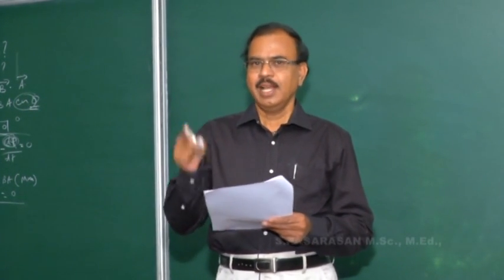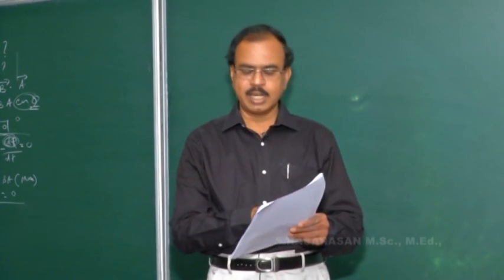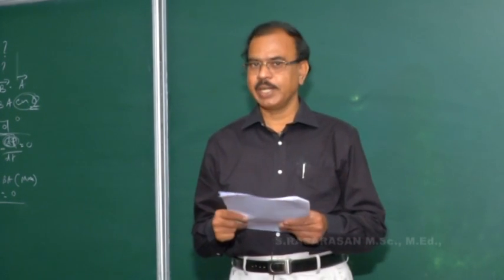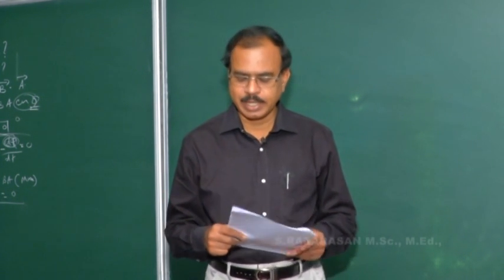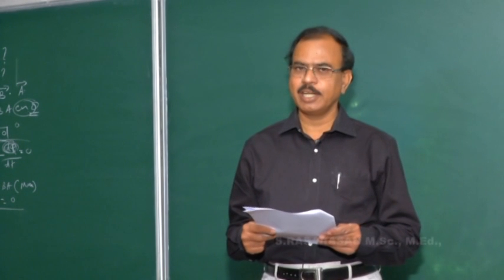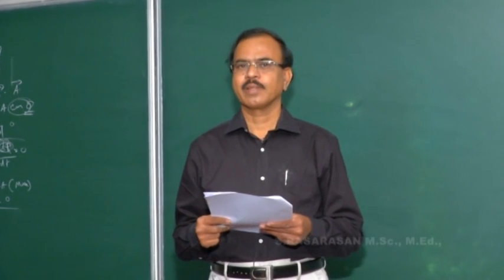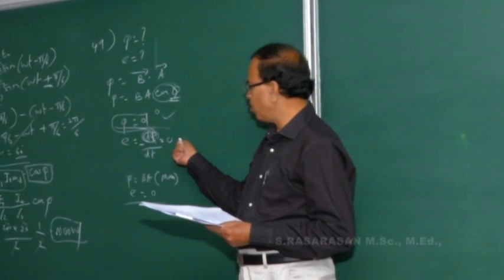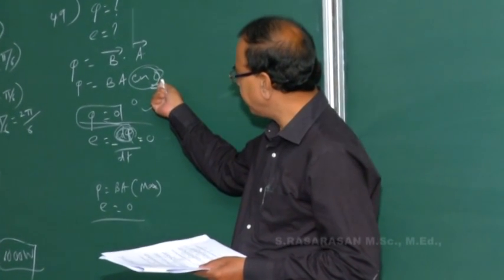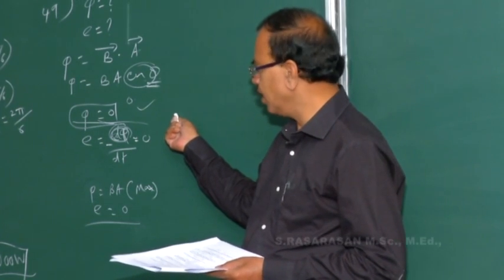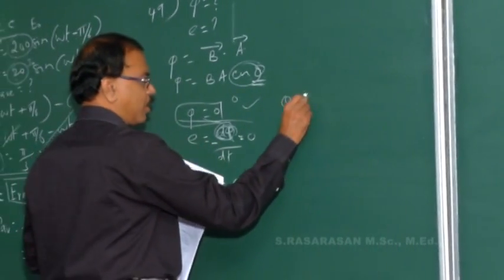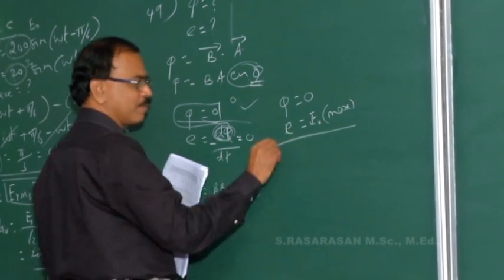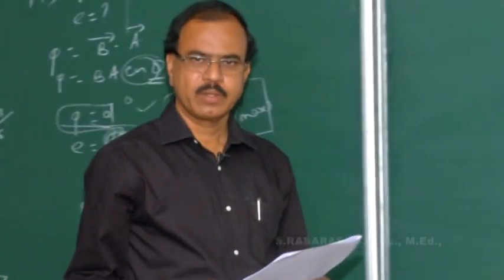It keeps rotating. At an instant, if the coil is parallel, the same question, since the coil rotates, then certainly the EMF is E equals minus d phi by dt, E naught sin omega t. So saying flux is 0 was correct first. Now E equals E naught sin omega t, and sin of theta, you said 90. Putting the same 90 here, sin 90 is 1. So phi is equal to 0 and EMF induced is equal to E naught. That is 0 and maximum will be the answer. So, 3 different ways.